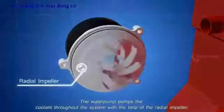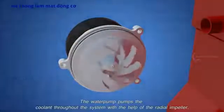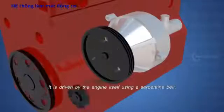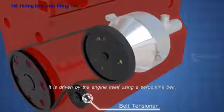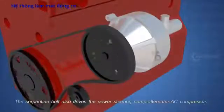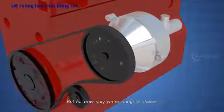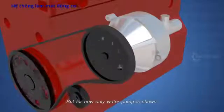The water pump pumps the coolant throughout the system with the help of the radial impeller. It is driven by the engine itself, using a serpentine belt. The serpentine belt also drives the power steering pump, alternator, and AC compressor. But for now only the water pump is shown. Now let's see the connections.